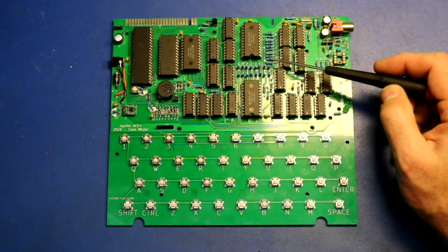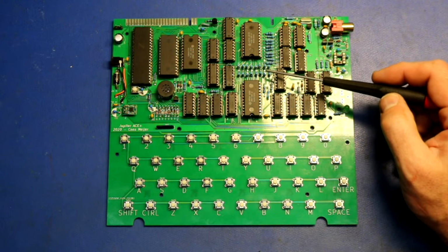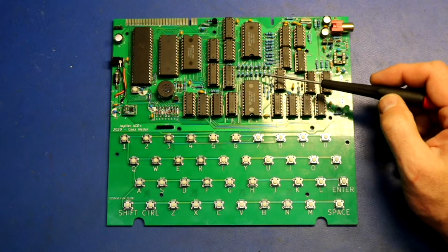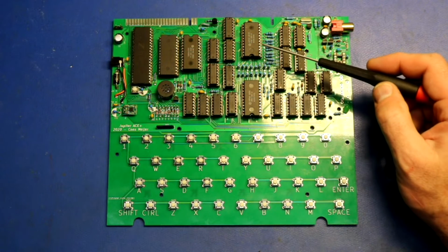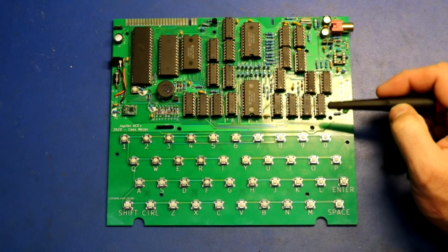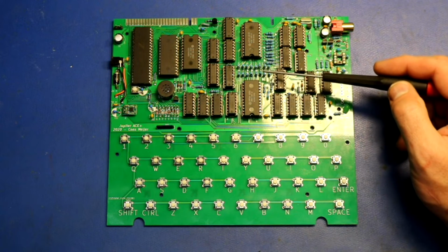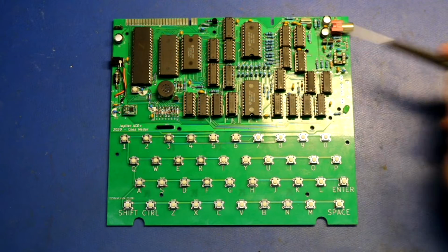And they do things in what seems to be a strange way, possibly just to save money on chip count and avoid a few bus transceivers. They would put data lines through a resistor and then multiplex that with something else, so that the something else would override the data lines, but when that went high impedance, the data lines could take over through the resistor. It's a little bit funky, but it seems to work just fine.